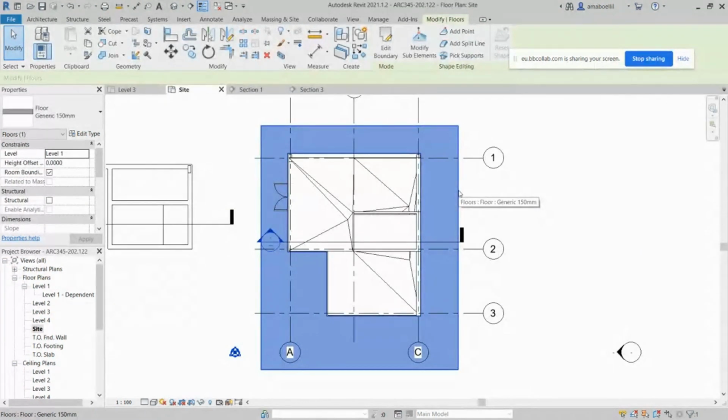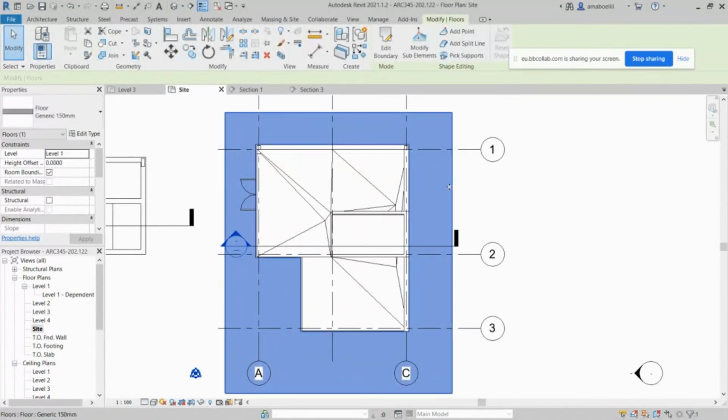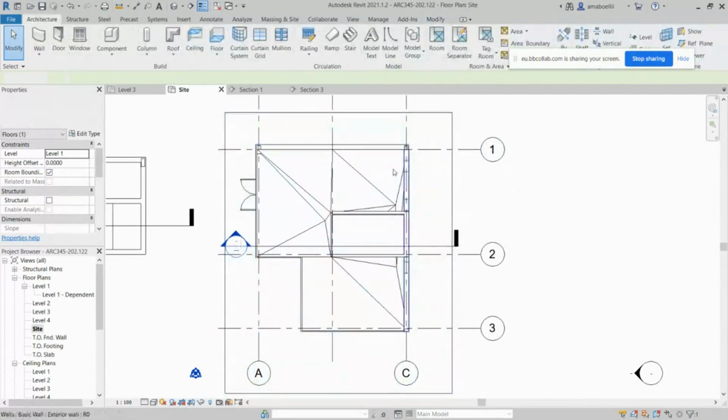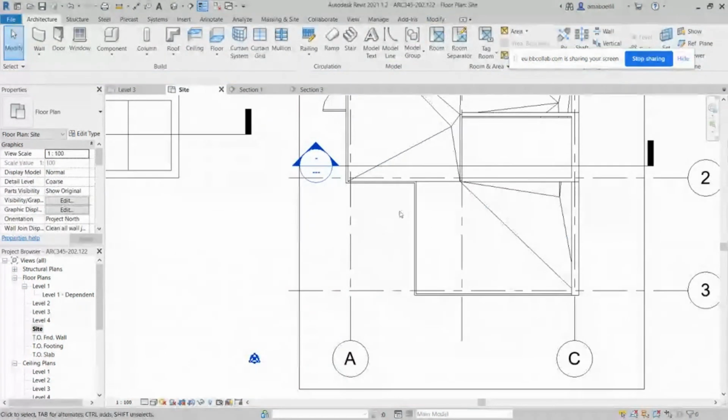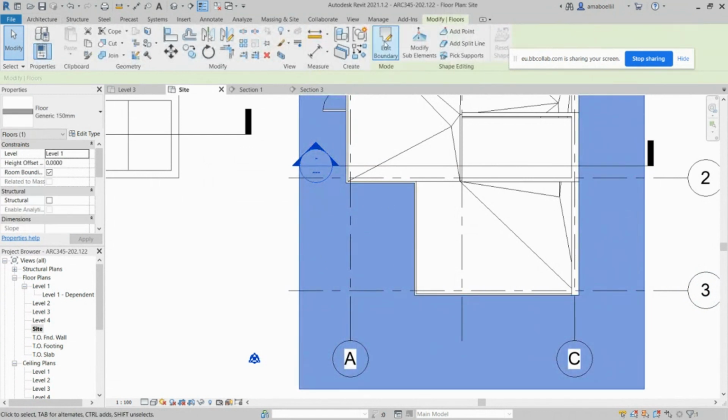The reason I said so is that if you want to now build your green area or build some tiling, you cannot do this unless you're having a floor, and the way to do it is just to create a slab and then to start to add to it the elements that you want to have. So if you are having, for instance, a green area here, you can create a hole similarly to what we did, create a hole in that, and then add another slab in between, so that you can go with the boundary.